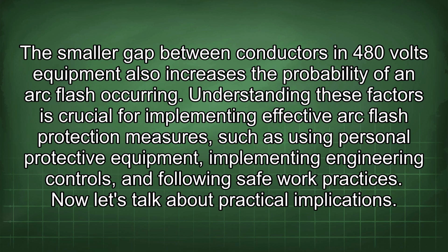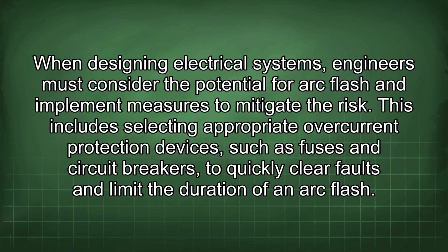Now let's talk about practical implications. When designing electrical systems, engineers must consider the potential for arc flash and implement measures to mitigate the risk. This includes selecting appropriate overcurrent protection devices such as fuses and circuit breakers to quickly clear faults and limit the duration of an arc flash.